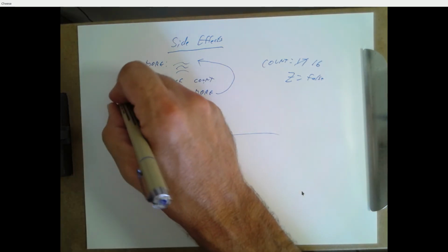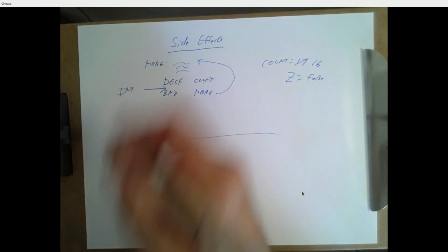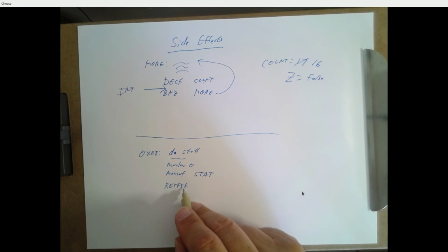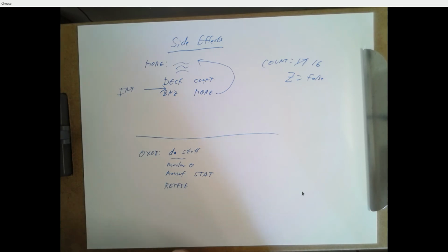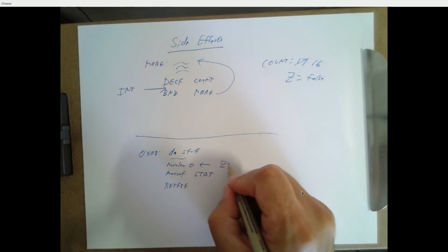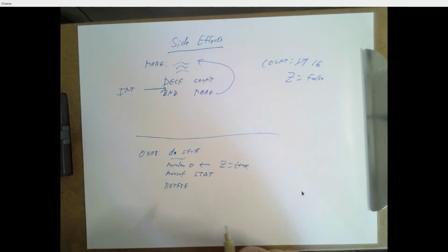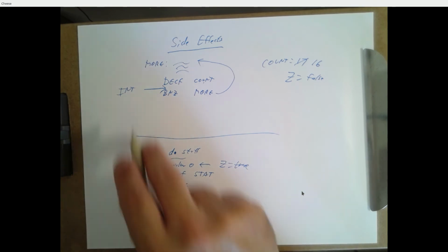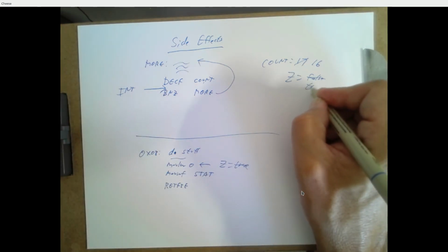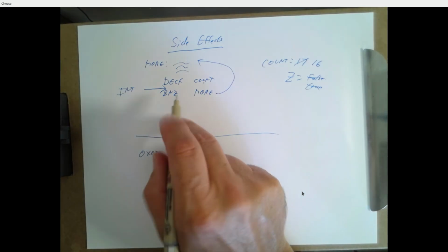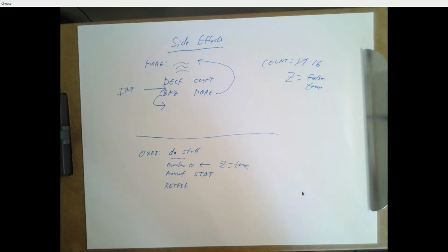But suppose right here, I suddenly get an interrupt. I jump down to location 8, I do some stuff. At the end of my stuff, I put a 0 into W, I put that into a file register called stat, and I say return from interrupt. What is the Z flag right now? See, when I did this move literal W0, that set my Z bit to be true. And when I move that into stat, the Z bit is true and I return. So when I come back from my interrupt, Z is true. And when I say branch if not 0, it's going to say, oh, Z is 1. It's not going to branch, and it's going to go on to the next instruction.